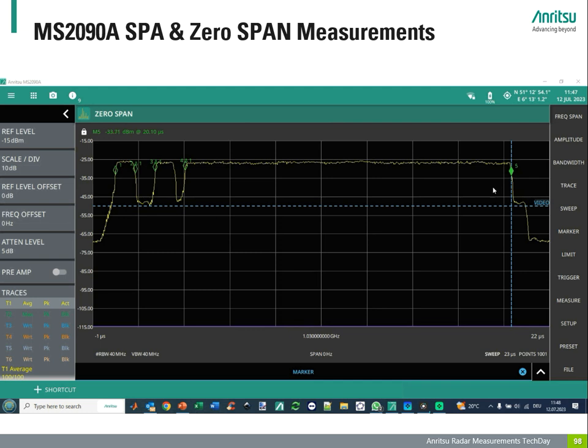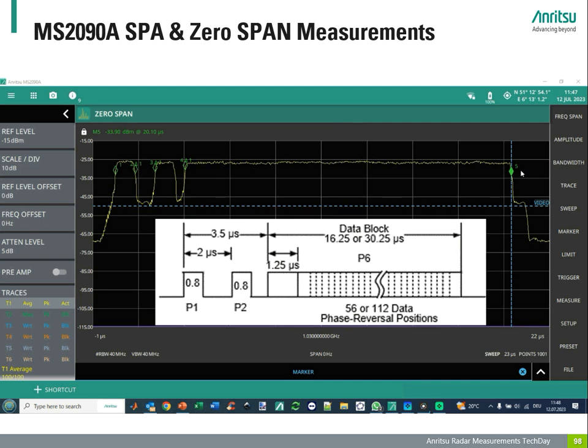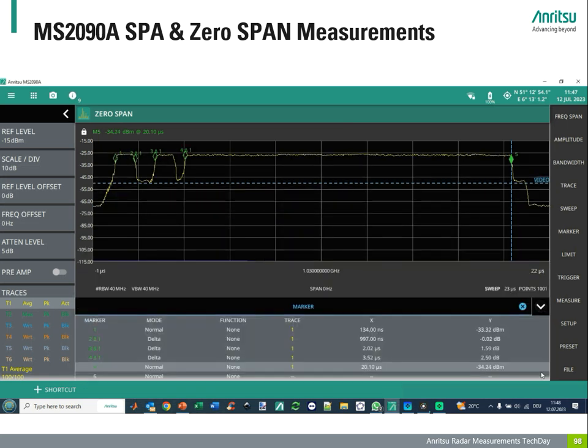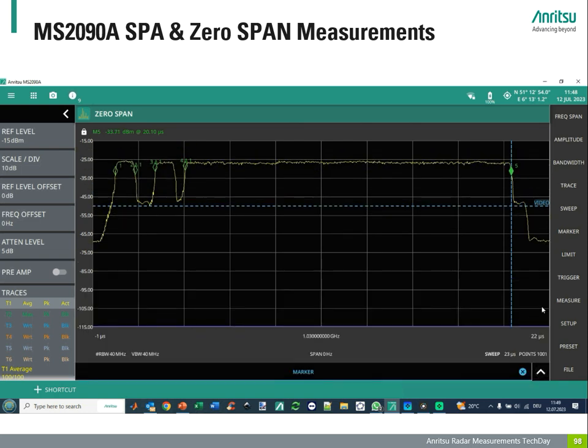You might remember the signal pattern of the ADS-B mode C signal. We can clearly see here a match of the signal shape, and the marker positions are confirming the correctness, which would be 19.75 microseconds. Finally, we also check for the pulse repetition interval, resulting in 19.95 milliseconds. A quite good match.